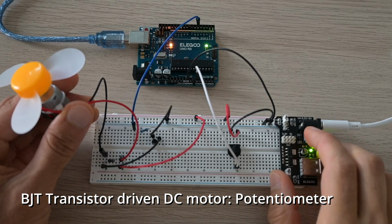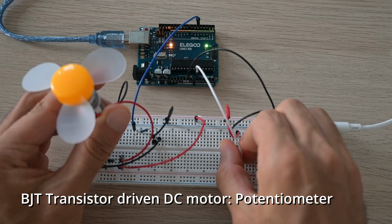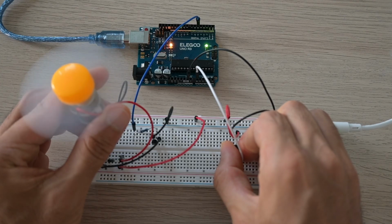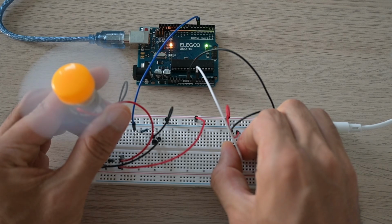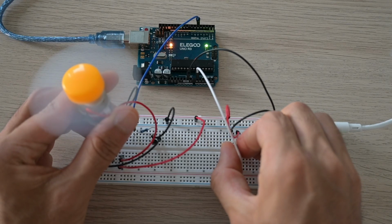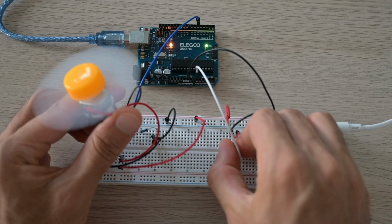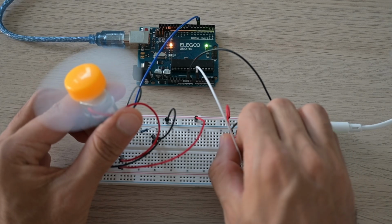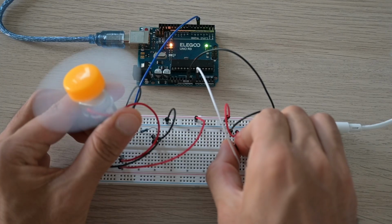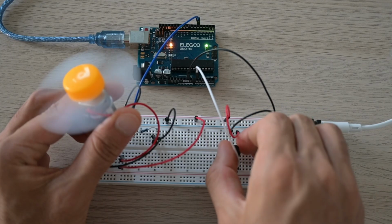And again, same setup as before, but controlling a DC motor with the potentiometer. Notice that I was not using a flyback diode in the previous video to protect the circuit from back EMF voltage spikes, which happen when the DC motor is switched off. And it is not the wisest idea when performing multiple tests. I was not aware of that effect at the time, but fortunately no harm was done. And from this video onwards, this was fixed, and the proper protection was added.